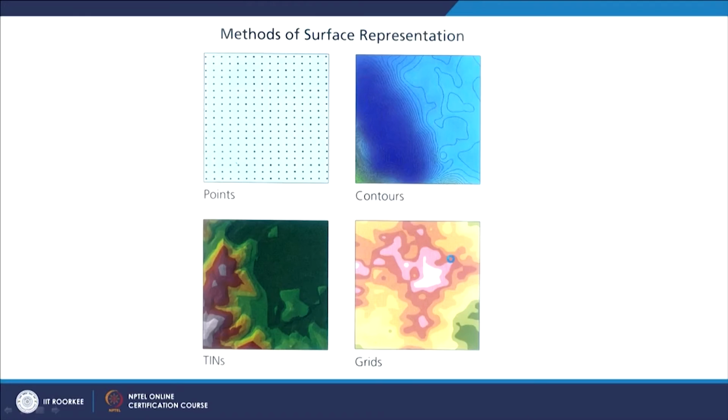If it is still in geometric domain, you would get geometric coordinates. Generally, if you download a digital elevation model, whichever free digital elevation models are available from different portals based on different techniques, all of them are nowadays georeferenced. So for each point location or each cell location, you not only get the Z value, but you also get X and Y in terms of latitude, longitude.